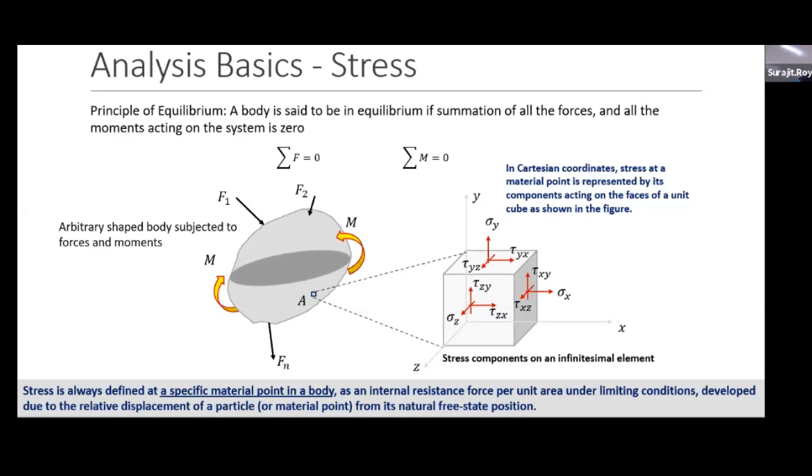When you have different plies stacked together, they have different modes of failure. So if you change the design, if you change the ply stack-up sequence, the failure modes will be very different. There is so much uncertainty that composites are not very easily or widely used. So those are basically the cons of it. Are you getting what I'm trying to say here?